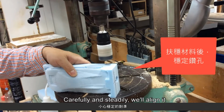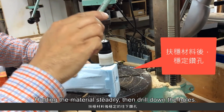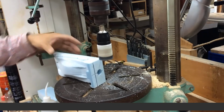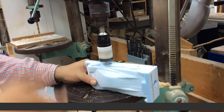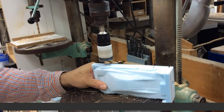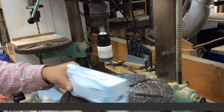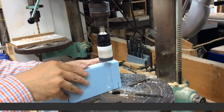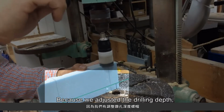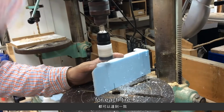Carefully and steadily, we'll align it to the position of the holes that need drilling, holding the material steadily and drill down the holes. Because we adjusted the drilling depth, we can achieve the same drilling depth for each tire.